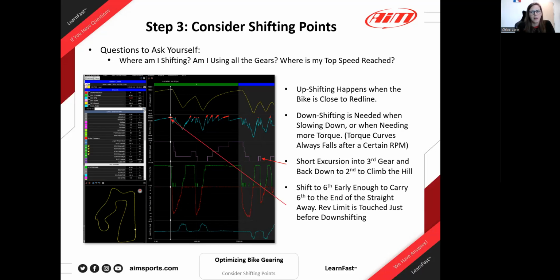Superbike, maybe. So what you showed here was that you can get all of this perfect in the important areas, the best you can do, but there may well be some spots where this is just imperfect, right? You're having to do a quick upshift and then another, and then right back down, and that's part of the balancing, the compromise of getting everything else right. If you were allowed to change your internal transmission gear ratios, if this is 3rd gear, you might be able to throw a little longer 2nd gear in there where you could have run that one all the way up there or something. But it's pretty in depth at that point.